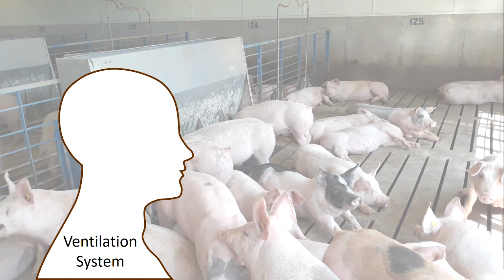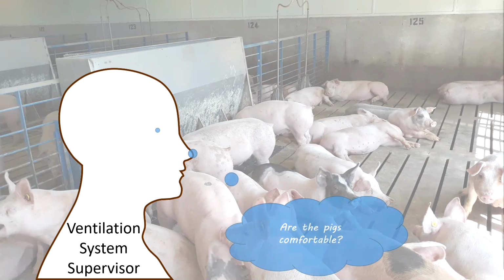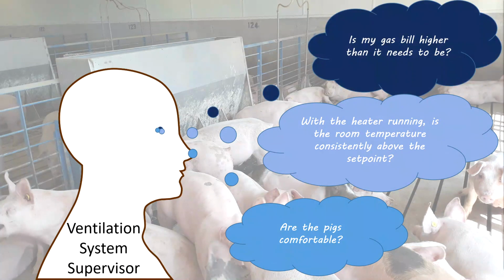The ventilation system may be an unseen employee in a swine operation, but the controller still needs a supervisor, providing review and guidance on how the controller should react to certain situations. There are things the controller cannot sense or make sense of with its temperature probe alone. So regularly check in on a ventilation control system, keeping in mind how the differential, bandwidth, and offset settings work around the controller set point, but also with each other. These settings make a difference in how quickly the ventilation system components react to changes in the barn and surrounding environment, and how much heat and electrical energy we use in the process.